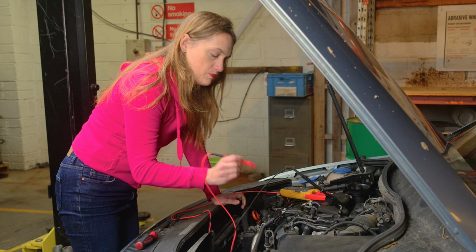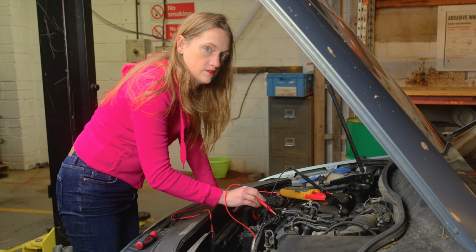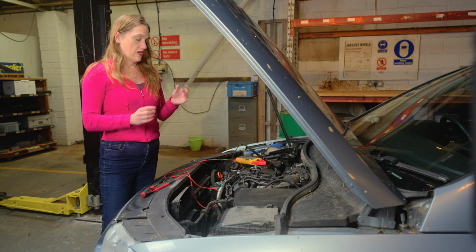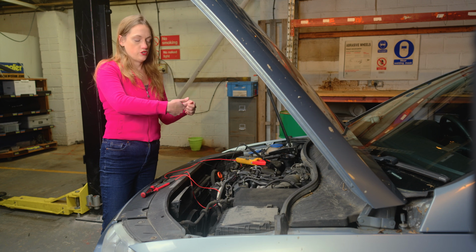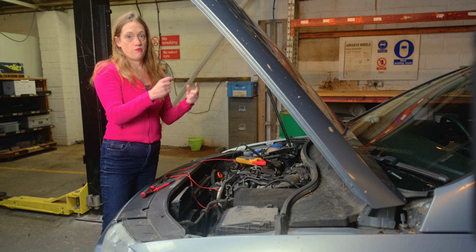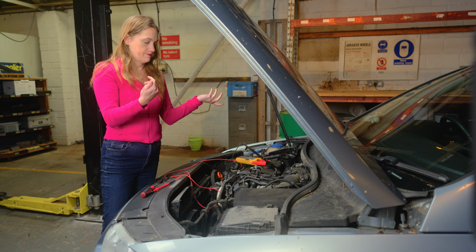What we need to do is do a pull test on that wire and then have a really good close look at the other one. Pull test is where we pull back the sheath around the wires, and we use a screwdriver to lever the wires and pull them. If the copper wire is broken on the inside, the plastic will stretch and break.